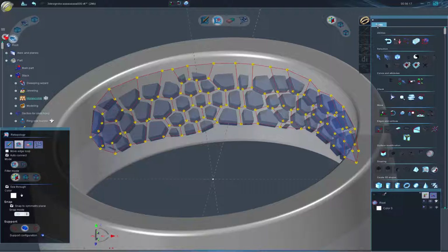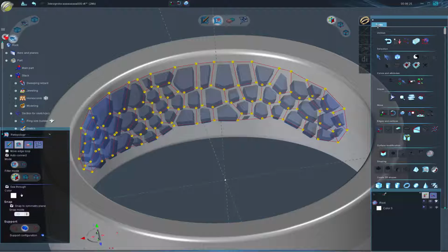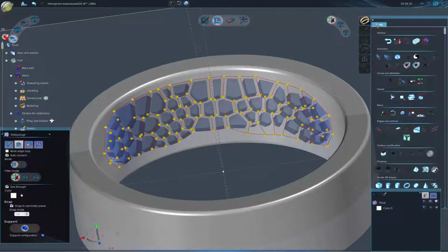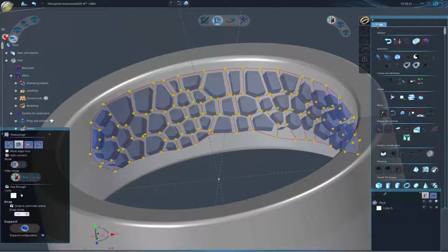Okay, remember V8, a lot of our tools we can now recalculate live, so if you want to see those changes, and just update as you go. Okay. And we'll just go ahead and manipulate our pattern. I was hoping for a little more weirdness on some of these shapes, but it seems like other than some of the tiny ones, this one came out pretty good. You will have to sometimes maybe unfold some points. You'll notice when you convert it to the mesh, you'll see some of your points are crisscross. So again, that'll fix any of those weird issues that you had from the auto calculation of your honeycombs.